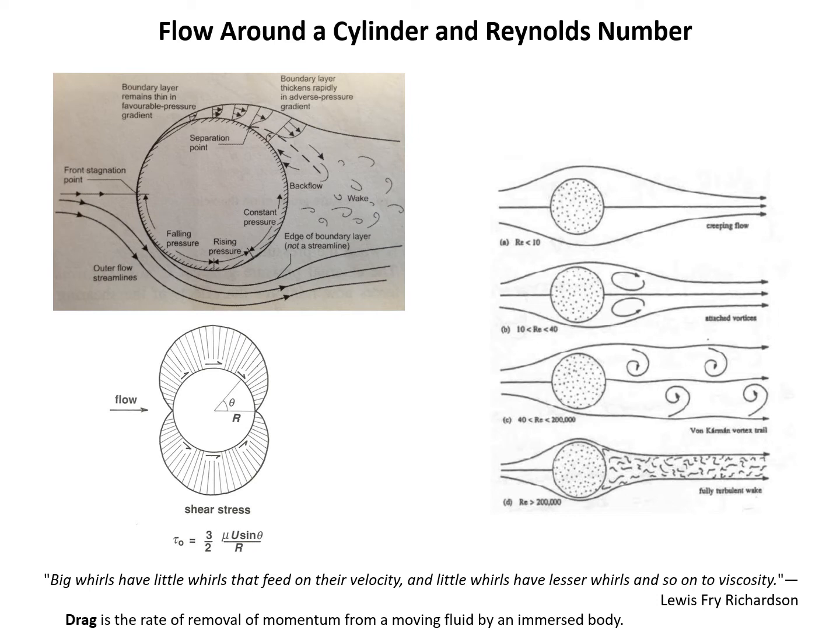At low Reynolds numbers, something less than 10, there is no separation. And because of that, there's a lot of recovery of that normal force. So the pressure that you're pushing on the front of the cylinder in the upstream side is recovered by the pressure pushing on the cylinder on the downstream side.